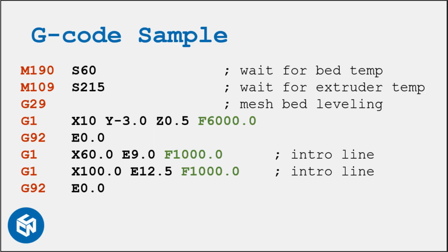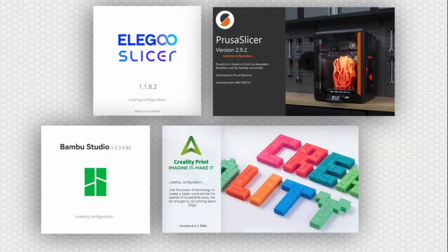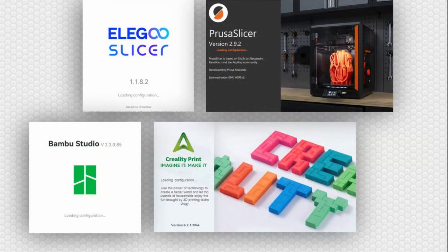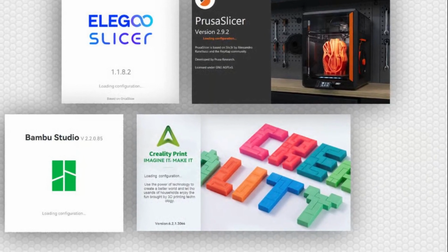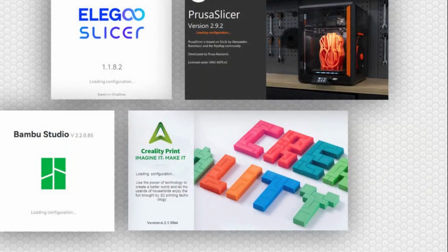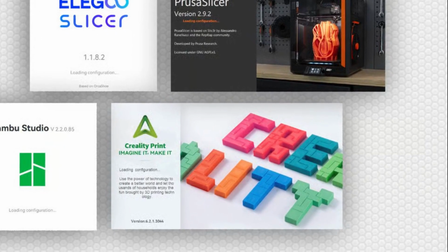At the very end of slicing, everything is compiled into G-code. G-code is not smart. It doesn't know about models, layers, or infill. It's a low-level instruction stream. Move here, extrude this much, set temperature, turn fan on, wait. All the intelligence lives in the slicer. This is why two slicers can produce very different results from the same printer and the same model. They have different assumptions, heuristics, and priorities. Some favor speed, some favor surface quality, some are tuned for specific hardware ecosystems.